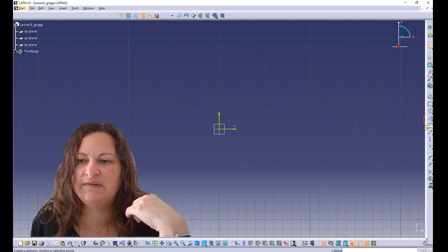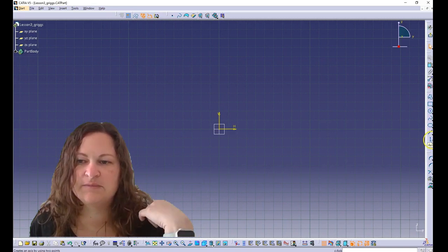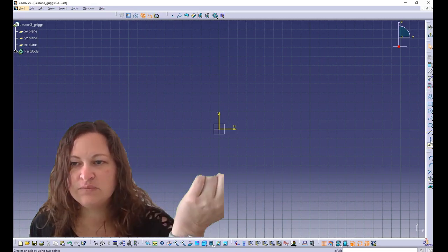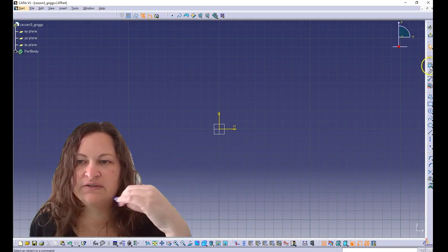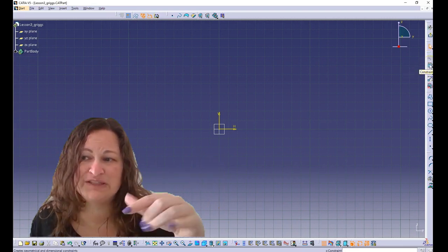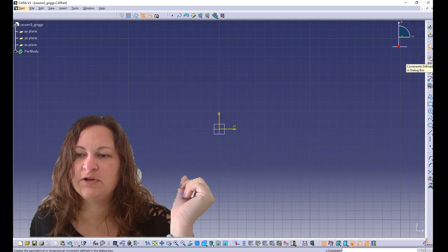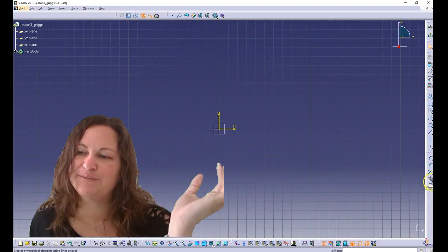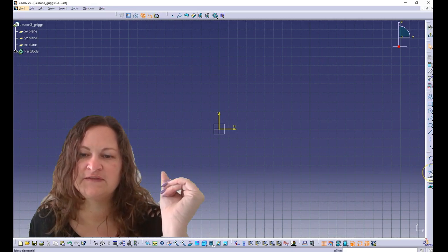Then you have reference geometry like an axis that you can add and helps you with some of your constraint generation, which is done using the constraints toolbar. The dimensional constraints are just underneath the icon that says constraints, but anything that is geometric is going to be under your constraints defined in dialog box. You also have an operations toolbar, which helps you make some modifications to your parts, curved edges, and it helps you trim off some lines, make some reflective symmetry objects, things of that nature.